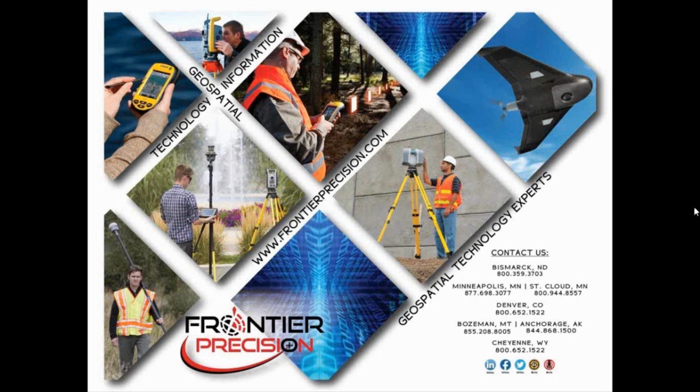But basically, the drafting module allows users to do drafting techniques. So we have a lot of customers that maybe use Civil 3D, but they only use it for drafting. So for instance, in Trimble Business Center, you could drop your data in, you could draw a plat, a boundary, put in a plot for your title sheet and border and things like that, so you can plot out to a plotter. So you can do drafting type of workflows with that module.